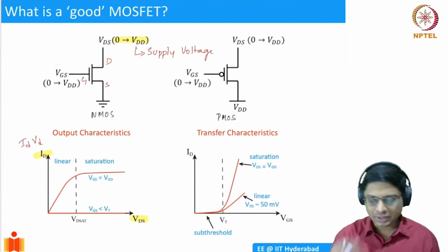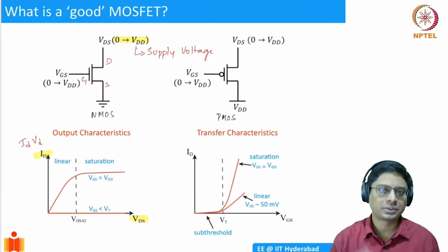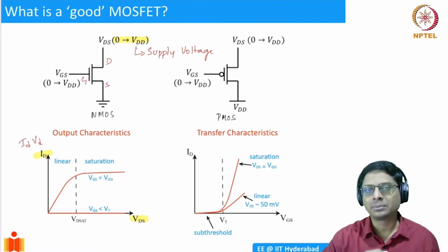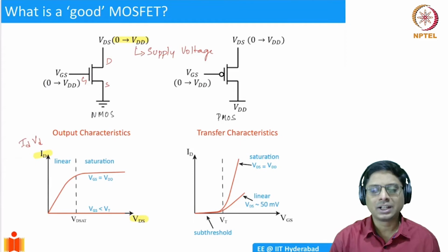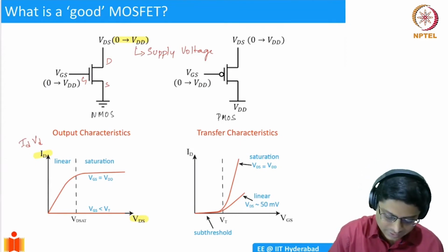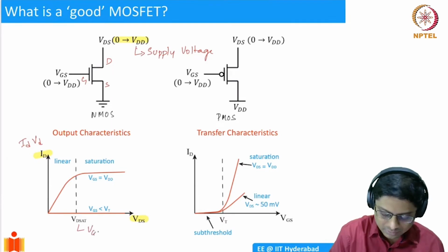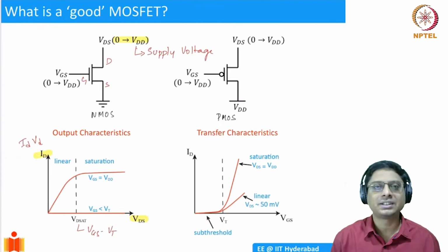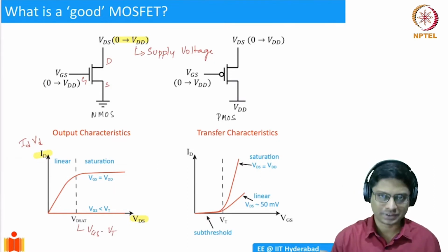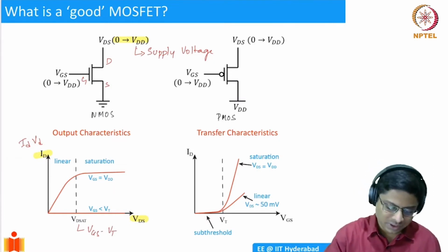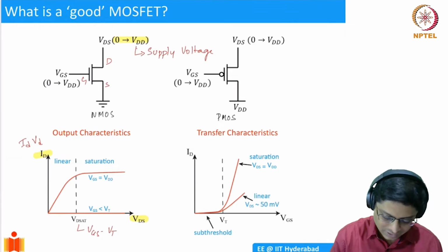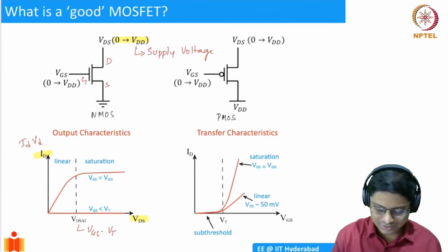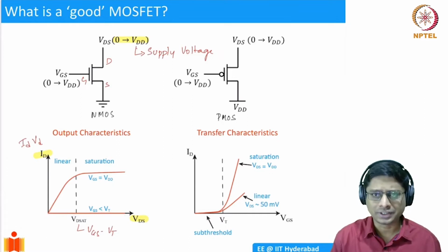While we do that, we saw that when the drain voltage is small, your MOSFET is biased in the linear regime, and then as you cross VDSAT, which we said is equal to VGS minus VT, if your drain voltage is greater than VDSAT, the current saturates. I have shown here 2 particular graphs. One is when your gate voltage is less than VT, we don't expect current, right?